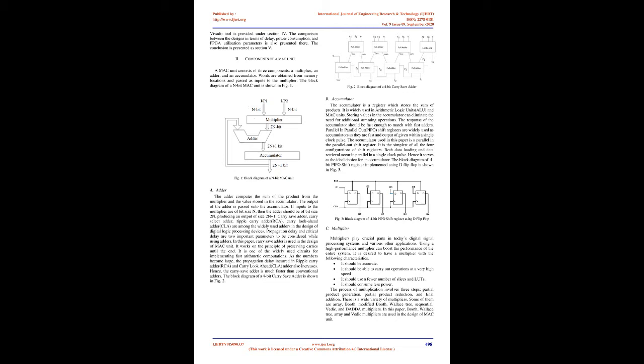In general, the delay incurred in DSP systems is mainly due to long multiplication processes in the multiplier. A wide variety of multipliers are known to be in existence. Each multiplier has a unique structure and follows a unique algorithm. Vedic, Booth, array, and Wallace tree multipliers are some of the multipliers that are being widely used. Analyzing and comparing these multipliers based on power consumption, the delay incurred, and area occupancy can help identify the optimum multiplier to be used in the MAC unit.